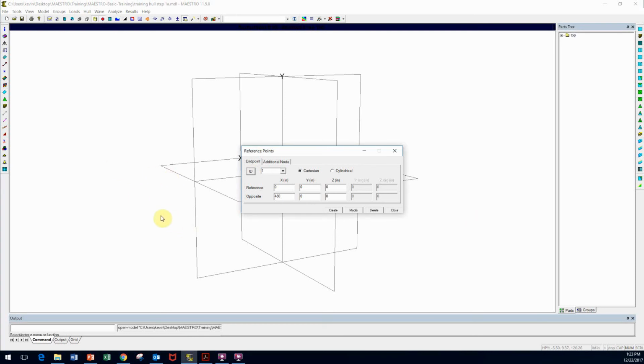And in this particular module, I had already defined the substructure and module coordinates, and that it was 6 sections of 80 inches apiece, so the reference end and opposite end numbers are already created. This particular endpoint is going to be on the keel, so the Y and Z endpoints will be 0. I hit create.